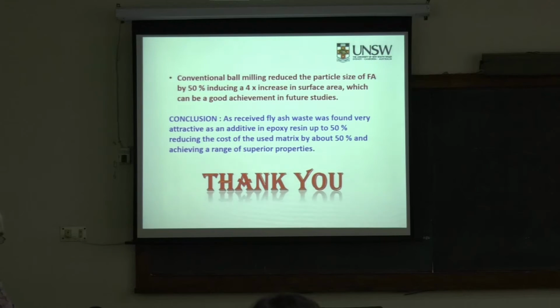And the conventional ball milling reduces the particle size of fly ash by 50%. That means by a factor of 2, and inducing a 4 times increase in the surface area. Which, yes?